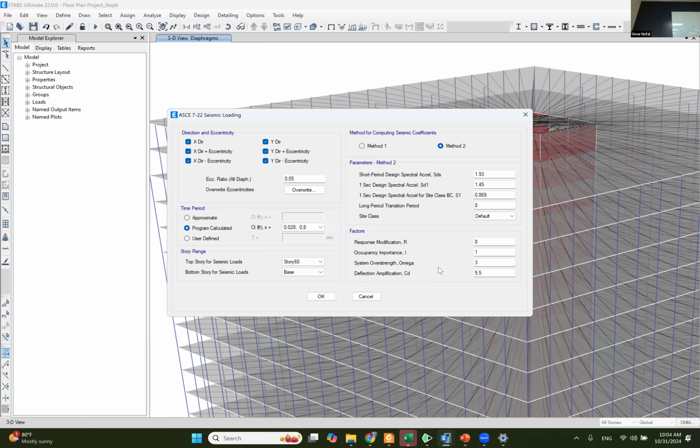Okay. But the thing is, when we do this, there's some stuff that adds stiffness to the building that we don't consider. Like we didn't put stairs in this building. We didn't model many elements in this model. So the standards tell you we are gonna assume there's an eccentricity, even if there's a shear wall here and a shear wall here, and both of them are on top of each other.